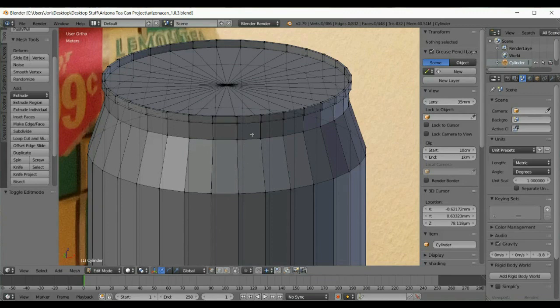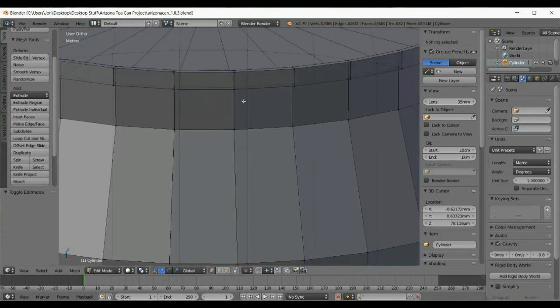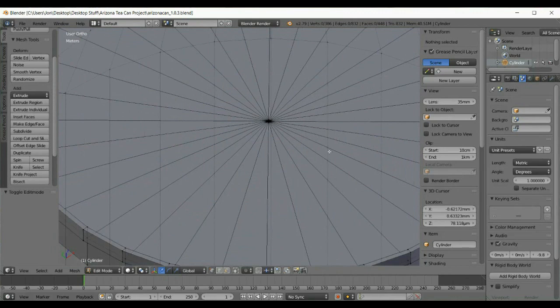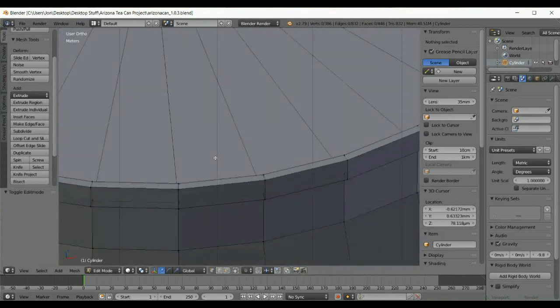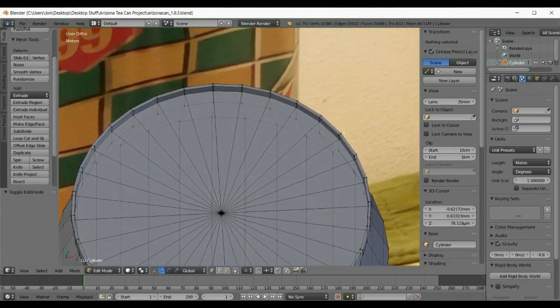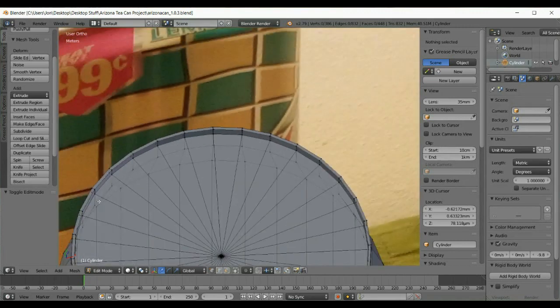But before I can do that, I need to mark this seam here. Now it's a little bit tricky actually, because if you see where this seam is, there's only one seam. See that? I'll zoom in a little bit here. See how good an angle I can get here. That's the wrong way to do this, maybe. There, see? This lip, if you will, connects into here. So if I mark this seam here, all I get is this surface, and I want to get the rim.